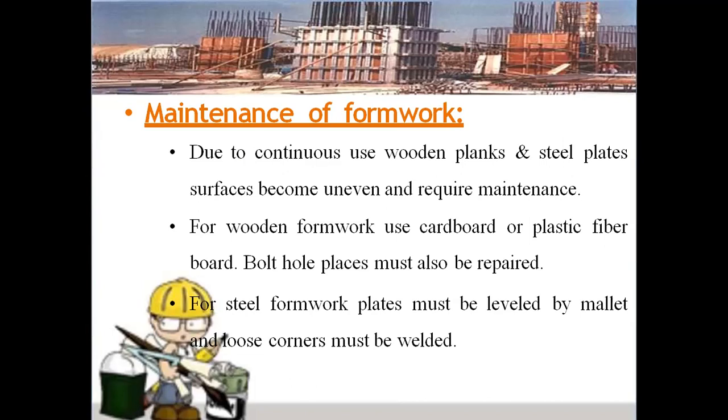When we are using wooden formwork or cardboard or plastic fiber boards in the formwork for the casting of concrete, the bolt hole places, where we drilled to join both formworks, must also be repaired after the removal of formwork from the strengthened concrete, so that these uneven surfaces also receive maintenance.